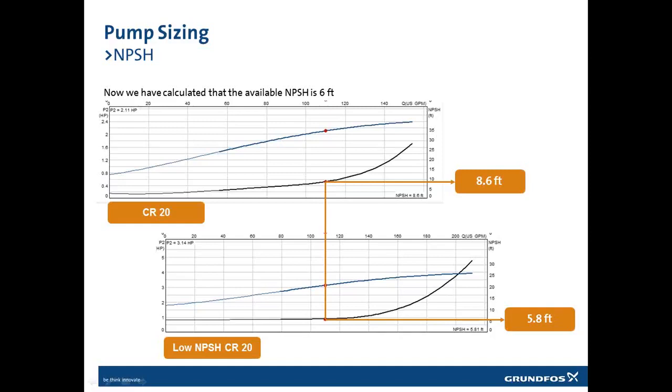In this equation I will say that I have added enough, because the flow I design with here includes the 1.25 times as catch-up. That means during normal operation I will never end up in this duty point on my curve.